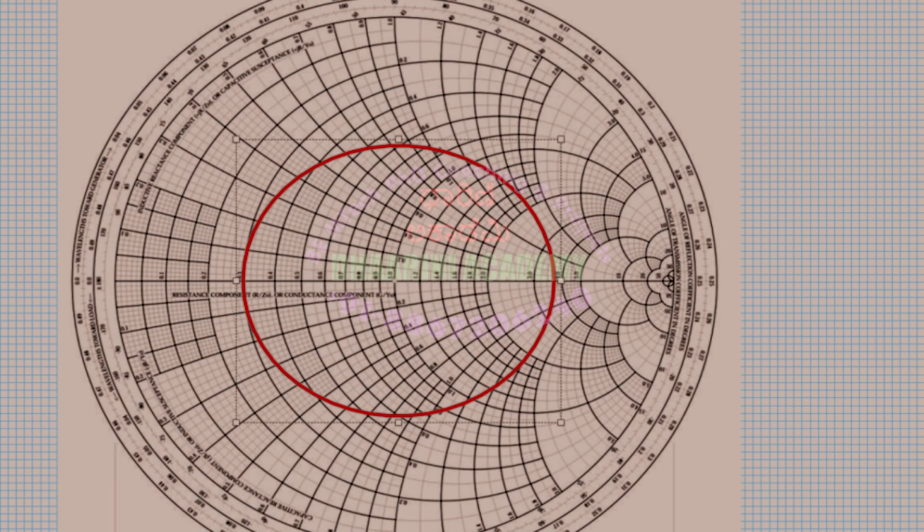So now whatever circle you see here, this is the constant VSWR circle. Is it okay? Right. Now the V min which was present earlier, where is the earlier location? This is the V min position. Correct? If you remember, where is the V min? This is the V min. Now they are saying that this V min moves towards the generator. Correct? This is going to move towards the generator.